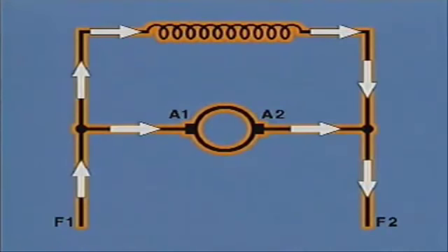If full-line voltage were applied to a shunt motor that did not have resistance installed in series with the armature, the resulting high current flow could severely damage the armature. Once the motor is up to its operating speed, the series resistance can be disconnected or bypassed.